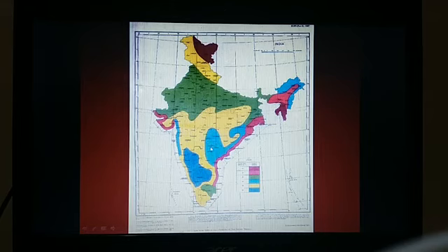So what is the wind velocity at this zone is given in this color, the sky blue color. In sky blue color it was given, I think the value is around 44. So the exact value we will see tomorrow in IS 875 part 3. Where almost your Andhra and Telangana is falling under pink color and blue color. So where you can find the wind velocity over here, okay, from this map.